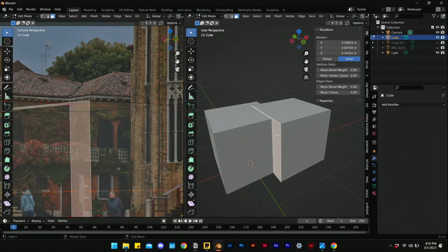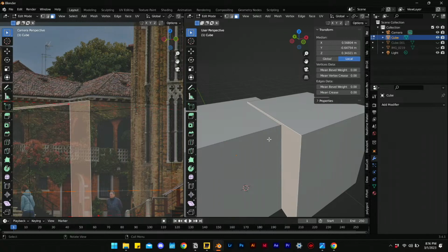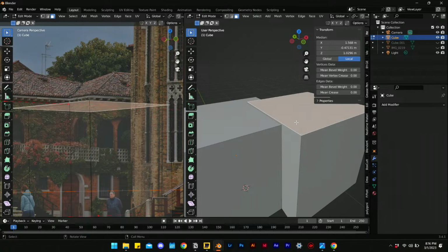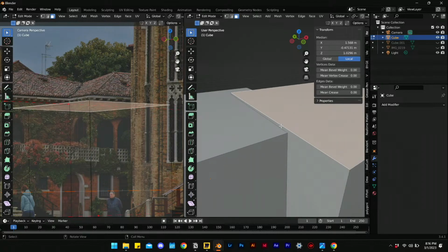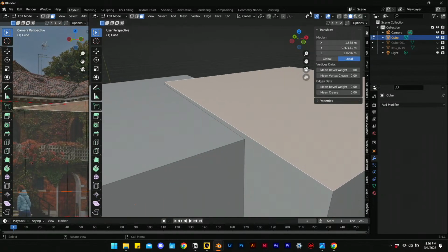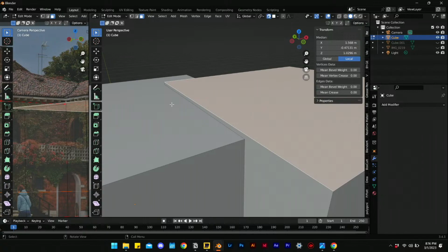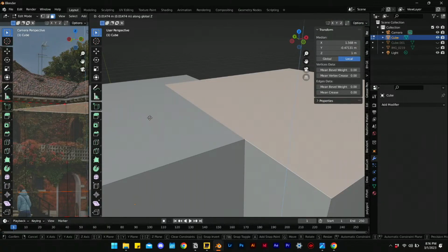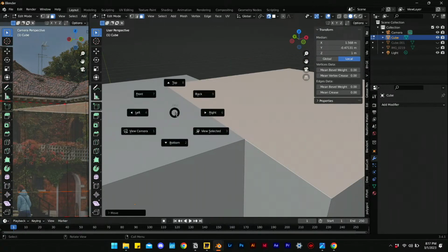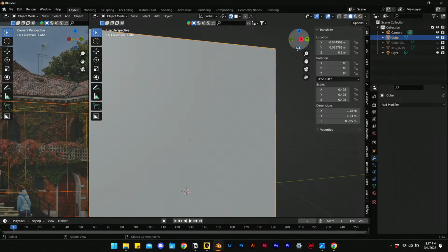And if I tab into it now, I have extra faces to work with, right? So I kind of messed up here with the heights, but that's okay. I can just select this top face over here and hit GZ, bring that down, or even better, if I were to turn on snapping. So I can turn on snapping up here and snap to face project. So if I hit GZ and I just hover over this face over here, it's basically just snapping onto anywhere on this plane. And there we go. We have them sitting at the same height.